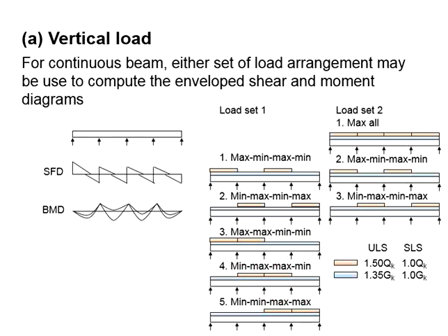Now, what defines the maximum and the minimum loads? Let's say we are referring to the ultimate limit state. The maximum load shall consider the existence of the GK and QK, while for the minimum load, there will be only GK. GK refers to the permanent load. Whether you like it or not, it will always be there, regardless of maximum or minimum. As for the QK, it is the variable action, which can be there and can be not there.